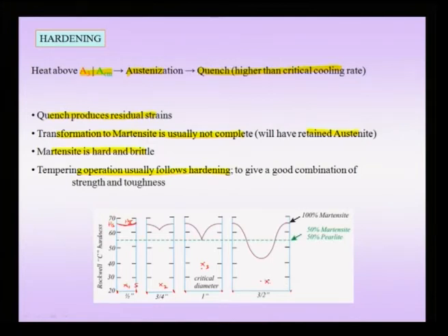So, here the x4 will feel an even slower cooling rate. So, I can write this down as T x1 dot is higher than T x2 dot is higher than T x3 dot is higher than T x4 dot. Even in the case, for instance, suppose I take a thick cylinder, the regions close to the surface are feeling a high cooling rate, but not the points close to the interior.